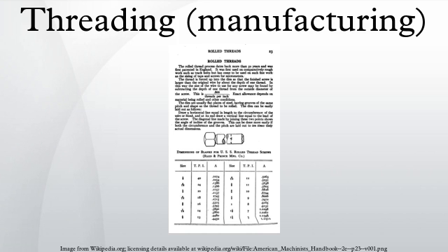Subtractive methods. Thread cutting, as compared to thread forming and rolling, is used when full thread depth is required, when the quantity is small, when the blank is not very accurate, when threading up to a shoulder is required, when threading a tapered thread, or when the material is brittle. Taps and dies. A common method of threading is cutting with taps and dies. Unlike drill bits, hand taps do not automatically remove the chips they create.